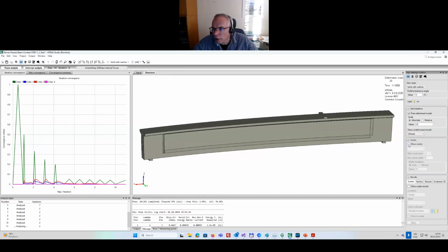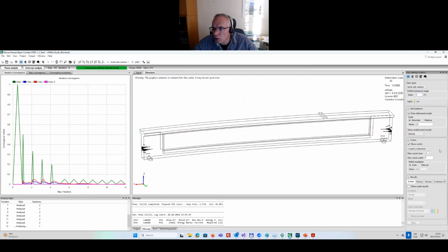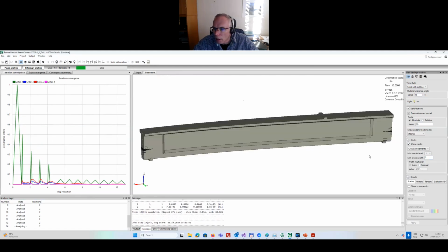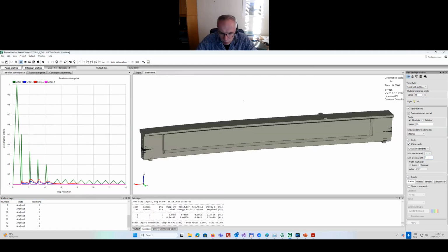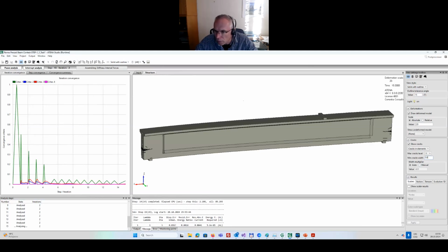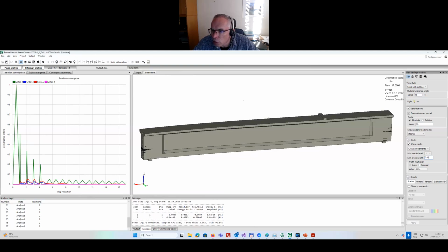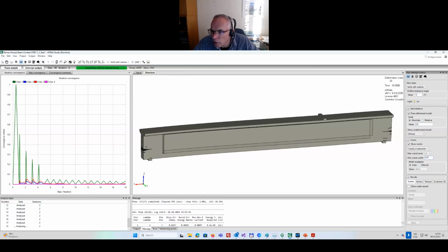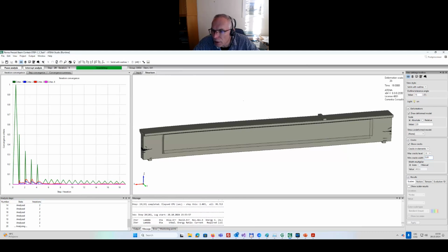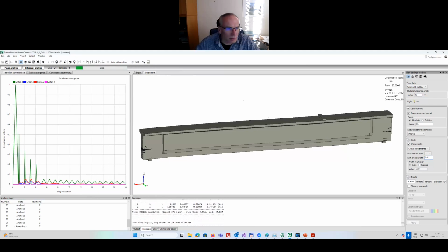Here I can also show cracks, and I like to show only the most important cracks. It's also always good to define some minimum crack widths. We are working in this model in imperial units, so the minimum crack width for, let's say, visible cracks, we can specify as 0.01 inches.